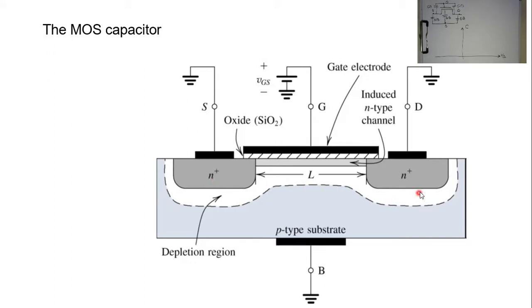Why? Let's turn to the other side, which is the drain side capacitance. Here you have positive N side drain and P-type substrate. The P-type is grounded and the N-type is connected to the drain. The N-type connected to the drain should be connected to a positive voltage in order to make current flow from the source to the drain. Accordingly, if you connect a positive voltage to the drain or to the N-type, that means that you turn this p-n junction into a reverse bias p-n junction.